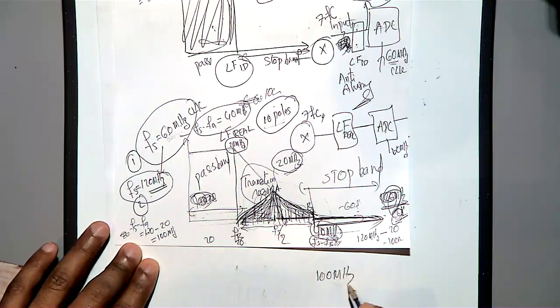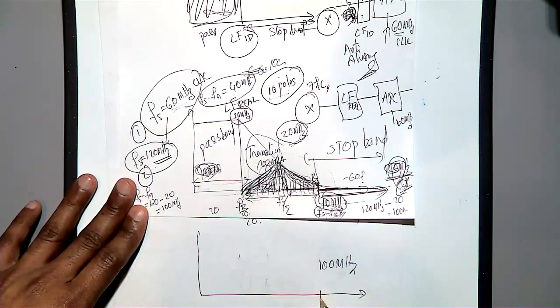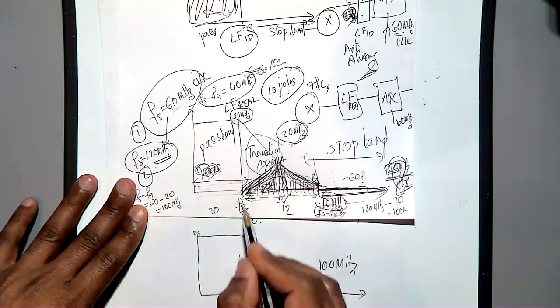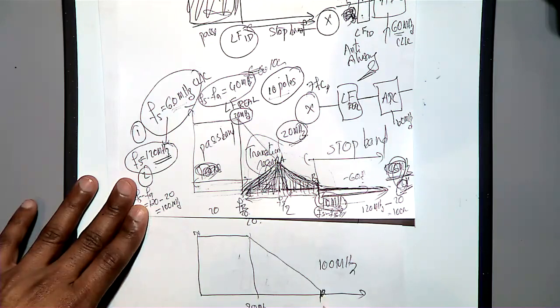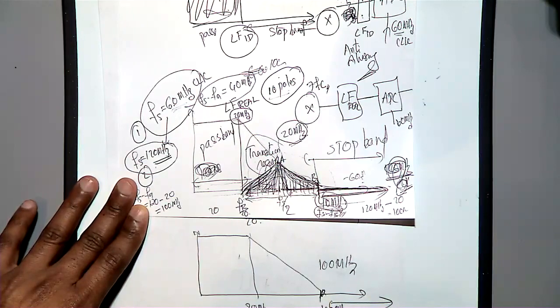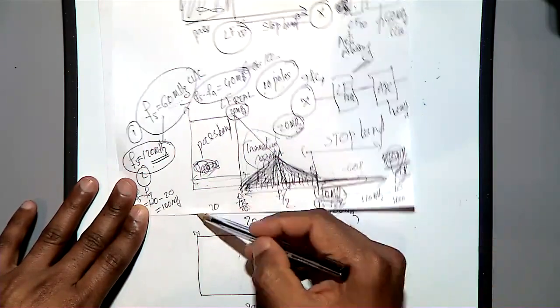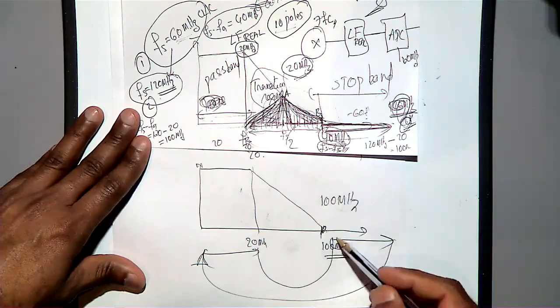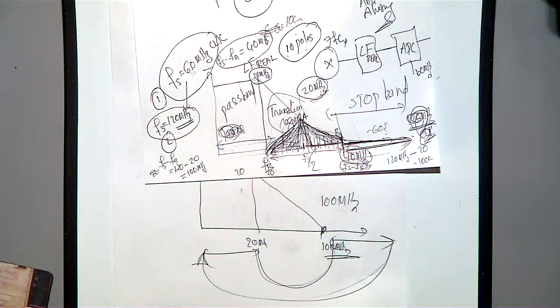See, now when you draw it, this is 100 megahertz. So now your filter is saying 20 megahertz, but you can have a less sharp transition region. Everything above 100 only will be folding back to this region. Previously everything above 40 was folding back like this. Now everything above 100 will be folding back like this. So you are pushing the stop band maximum frequency. You know what I meant?